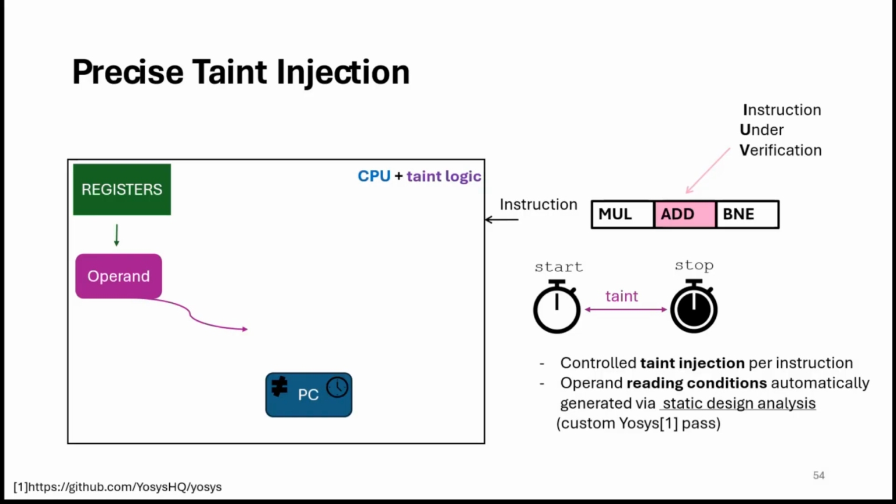So we don't need to rely on functional verification for when an instruction is expected to read from the register file. Instead, we extract from a specific CPU design the condition for when the instruction reads and when its value is updated again. We also don't use a changed-value check, because it could be reading the same value, or it could be the same instruction coming again. We really generate the condition for when potentially new data comes in, and then we taint.